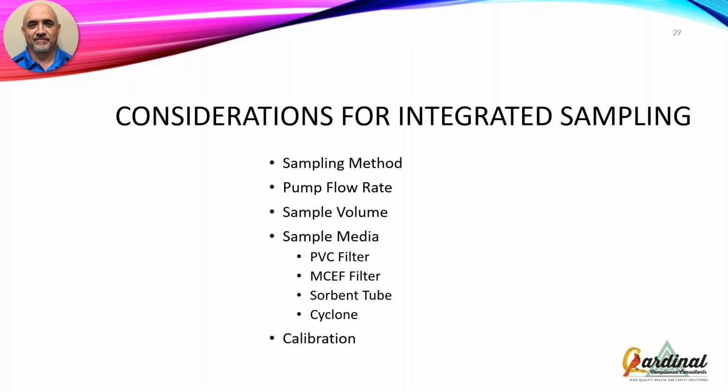And they're also going to tell me what volume, what airflow, and then at what volume, and that becomes important, because if I draw too much air through my filter or my collection media in a highly contaminated area, I oversaturate it. I oversaturate it, I can't read my sample, it voids it, right? It's just too much there for me to get an accurate reading. If I don't draw enough air through it, okay?